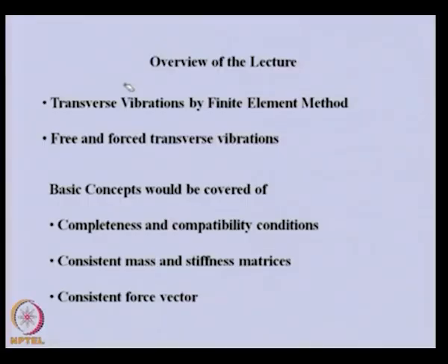Basically, we will be covering the transverse vibration using finite element method. Both free and forced vibration we will be considering, and similar to the torsional vibration case, various concepts of finite element method like completeness, compatibility conditions, and consistent mass and stiffness matrices will be derived. We will even be deriving the consistent force vector.